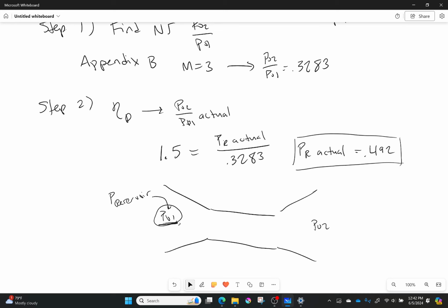If our flow at the end is moving very, very slow, so my Mach number over here is much, much less than 1, around about 0, but it doesn't have to be 0, it could just be much, much less than 1, well, you know what that means? It means that my total pressure should be equal to my static pressure, and therefore, my total pressure would have to be equal to atmospheric. And so we'll say in that case, 1 atmosphere.